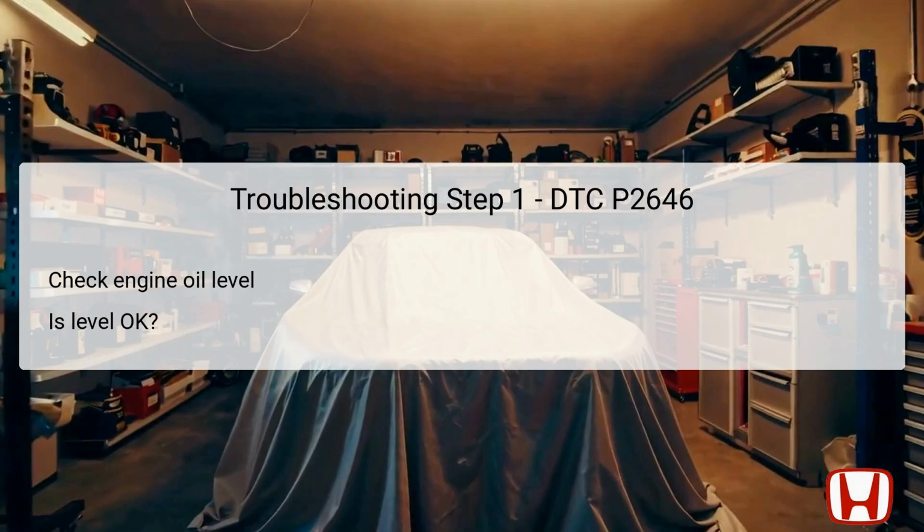Adjusting the oil level, if it's inadequate, is the first corrective action before performing any further tests or inspections. This step is vital to ensure that subsequent troubleshooting will yield relevant results, as low oil levels can disrupt engine functionality regardless of the conditions of the rocker arm oil pressure switch or related components.